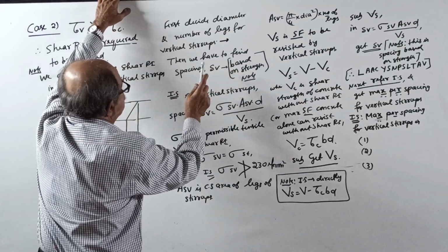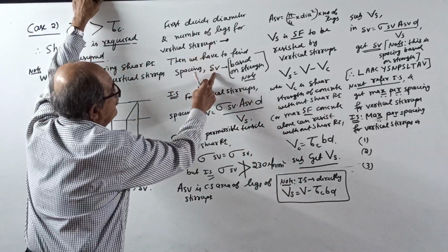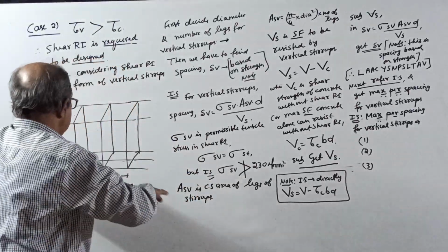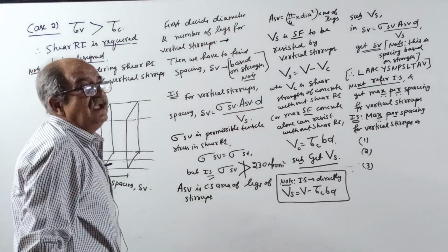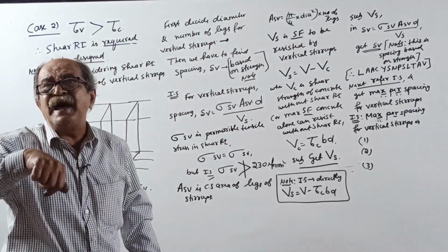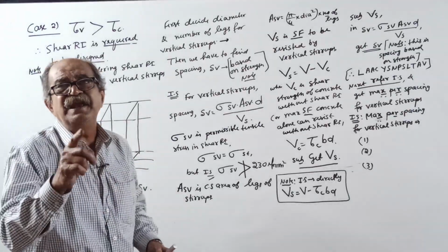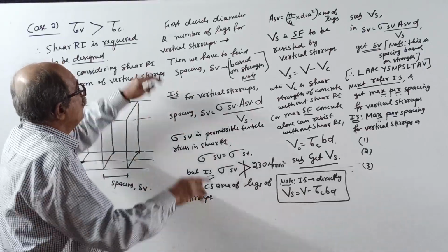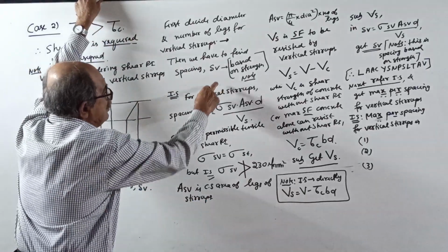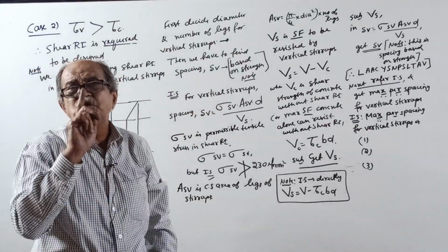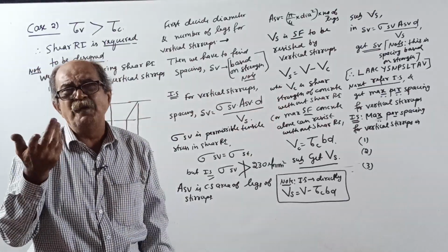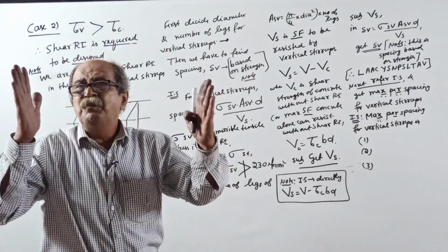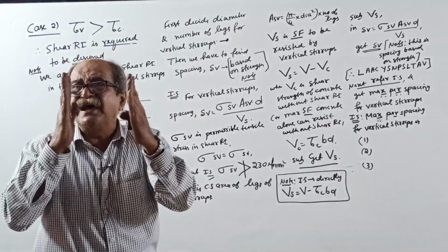Then we have to find the spacing SV. Remember, spacing SV based on strength. You should think a little. If the spacing becomes more, it becomes what? Lesser capacity. The beam will be stronger in shear strength when the stirrups come closer. Therefore, what spacing you get now based on strength, later you should not provide more than that. Common sense. Suppose you provide a spacing more, it becomes weaker. You make it lesser, let the bars come closer, stronger.